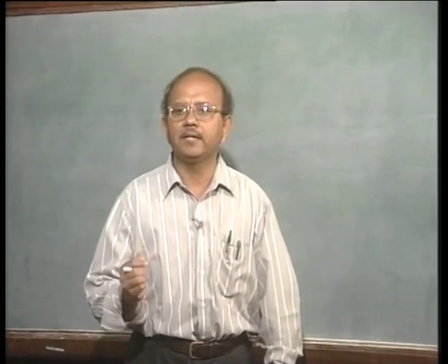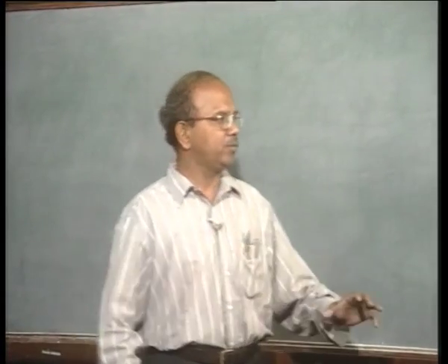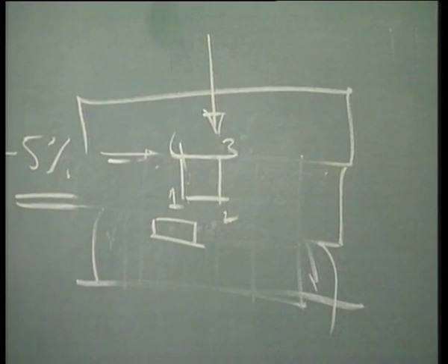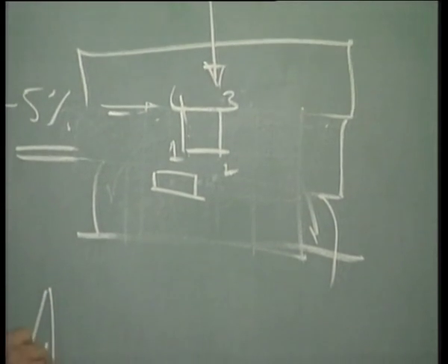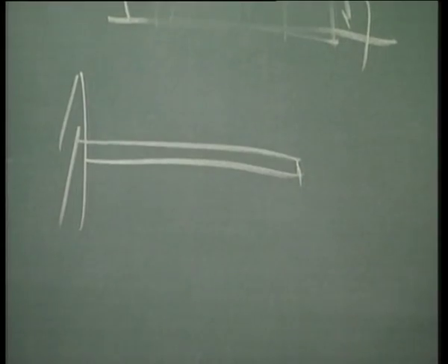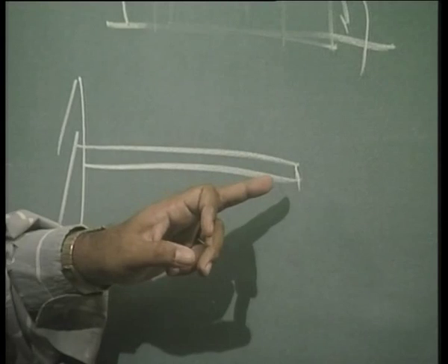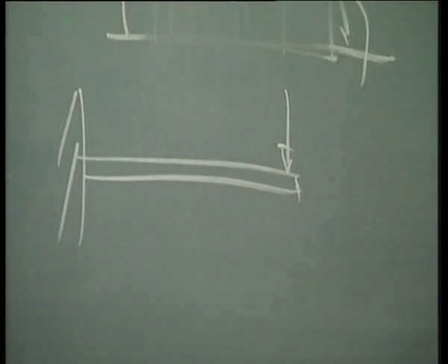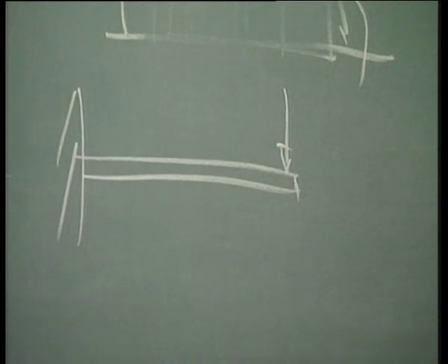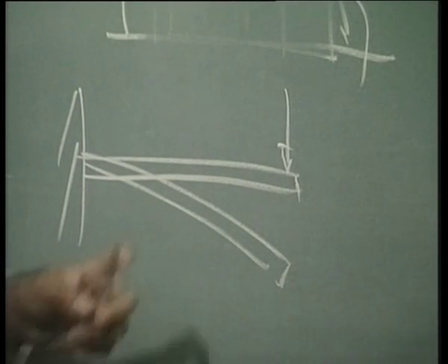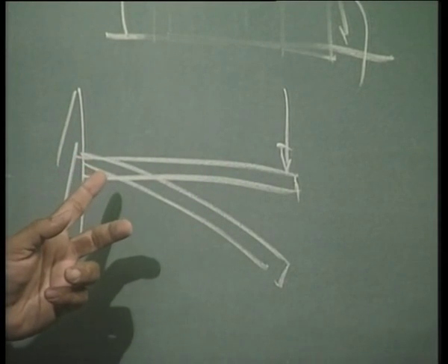Please note that it is not necessary that there should be a lot of strains in order to have a geometrically nonlinear problem. For example, if I have a cantilever beam, and it is a very, very slender beam, and I just apply the load, the deformations may be larger, or in other words the displacements may be larger, it may go like that, but still I might not have yielded.